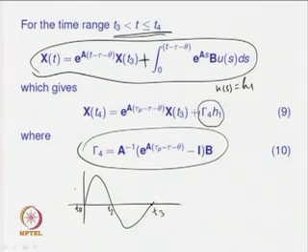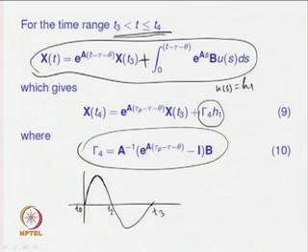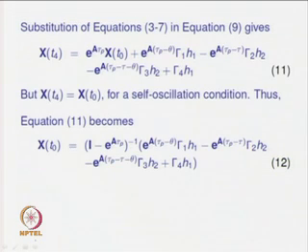So, using the set of analytical expressions, it is possible to obtain the exact sustained oscillatory output we get from the relay test. Now, using those analytical expressions, we can find the unknowns associated with the same second order plus dead time transfer function model. Now, that effort will be made. Before that, we need to find the value of the state at time t equal to t4.